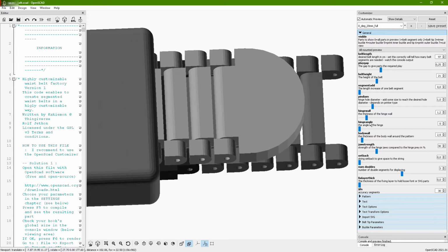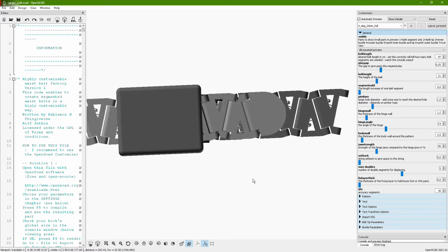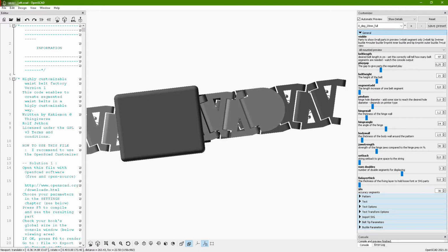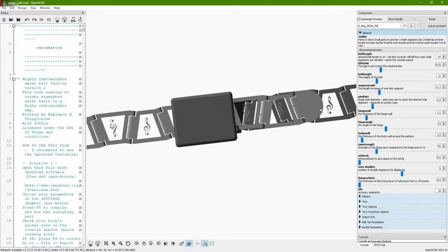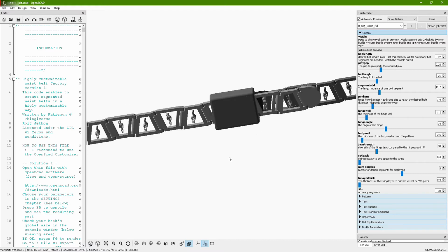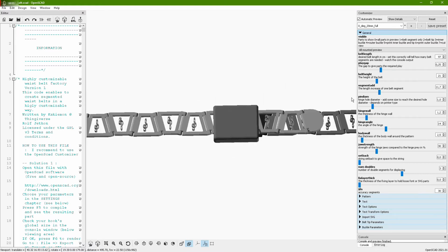But as soon as you start, for example, changing the hinge angle, the angle for the hinge, of course you suddenly get enough space. This is because, as you can see here, it's on 0, and so they're directly connecting these two slants, and they don't need an add. But you can also add something here. You can put some segment add here, then it will become a little bit bigger. You can define the sizes of your segments in a wide range.